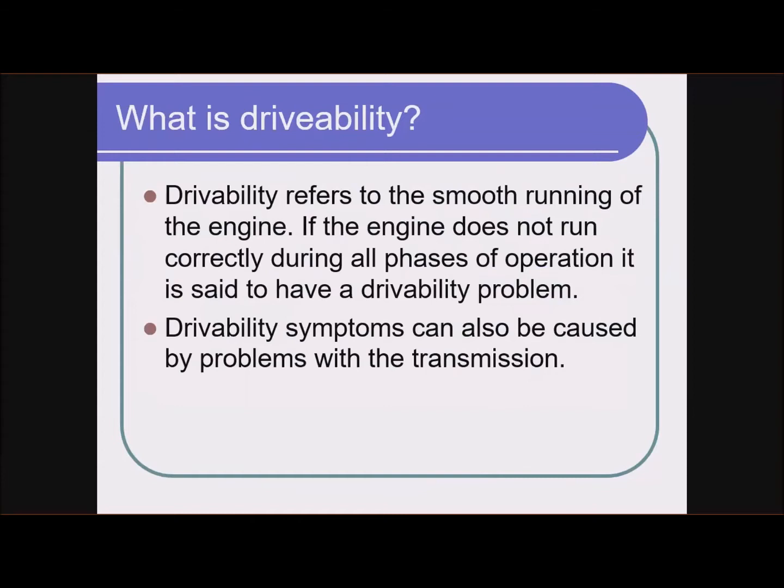Kind of calls into question how they determine Car of the Year, but anyhow, it had a unique feature for that year, 1984: an electronically shifted transmission. That was very uncommon in 1984. And this electronically shifted transmission had a problem where it had a fuse that supplied the transmission computer. And if that fuse, for whatever reason, popped, the transmission would default to high gear. Now imagine a 1.6 liter engine trying to start a vehicle out in high gear.